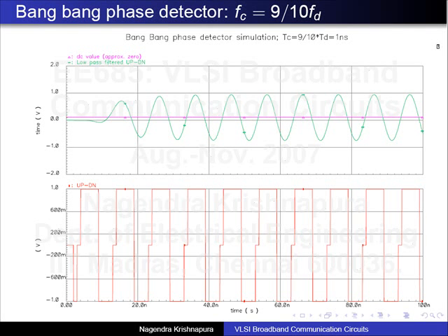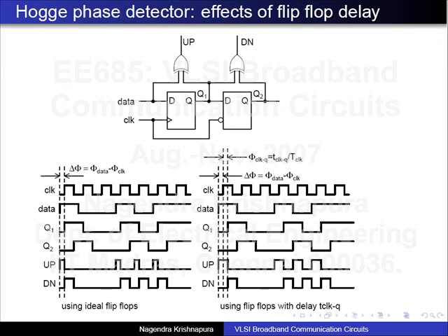Okay. So, in practice what is done is, when you have a clock and data recovery circuit, you have a frequency acquisition aid to this, because the range over which it can capture is quite small as a fraction of the data frequency. Okay. So, to speed up capture and to help in capturing, you have a frequency acquisition aid. I will show an example in a moment.